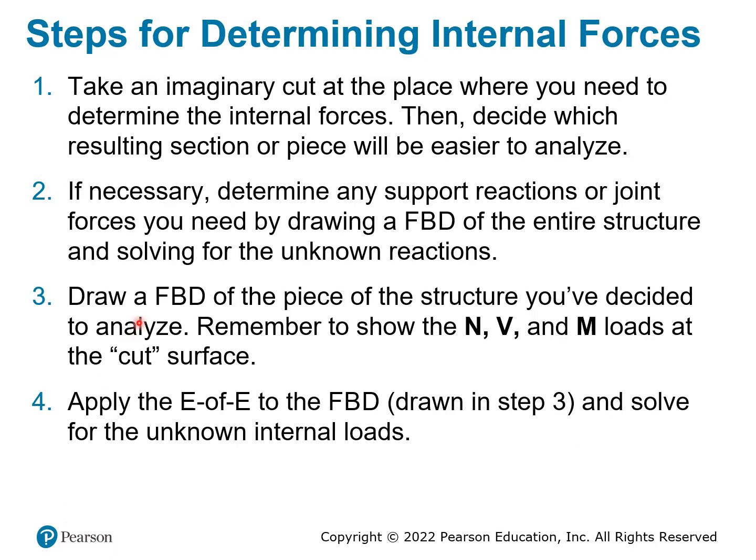Now, let's look at the steps to determine the internal forces. The first step is that you're going to cut the piece, take an imaginary cut. What you want to determine are the internal forces, so you have to make sure what the desired point is, and you cut that piece at the point that you are trying to determine.